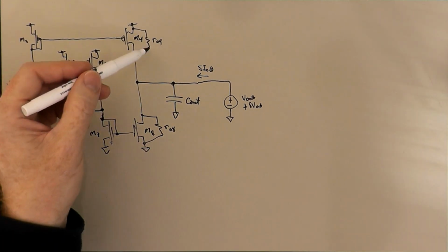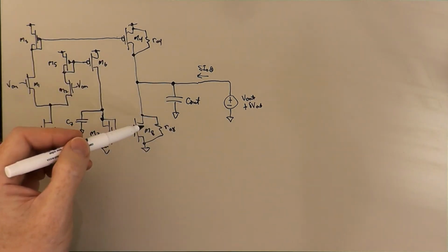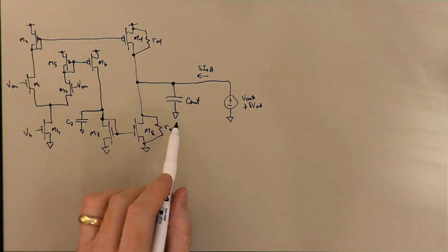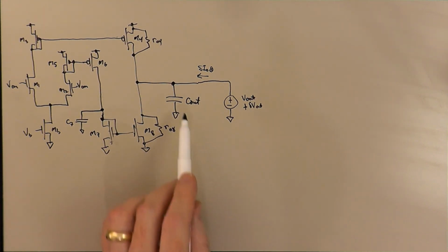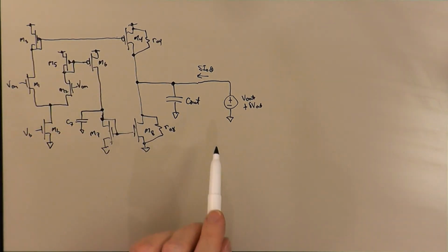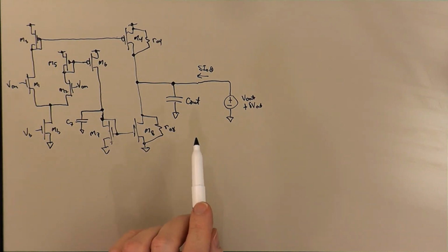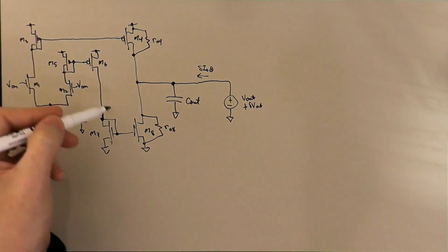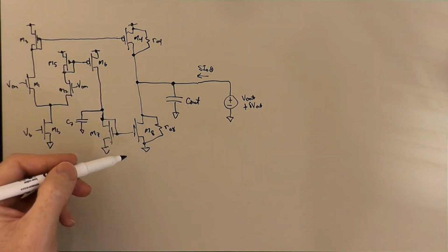I think it's pretty evident that if we were to go to the trouble to repeat the whole source splitting thing here with our four things and the added fifth thing connected to the output, splitting those into separate lines with replica sources here, the C out, and the early effect resistance and the two drains here, we would come to exactly the same Z out that we had a couple of videos ago, because effectively this capacitor over here is completely isolated from what's going on at the output node of the circuit.